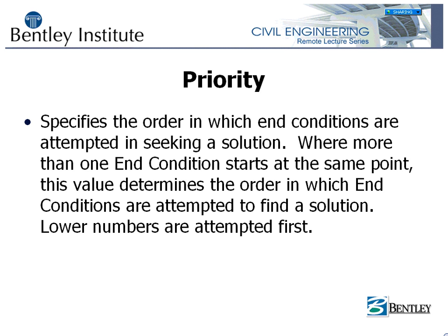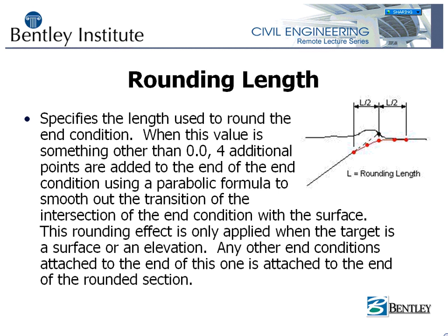And my final definition for this morning is a rounding length. We have the ability to do slope rounding now, which is just kind of neat to do because it happens on a daily occurrence, and many agencies require that you do slope rounding. And so we can set up a rounding factor, and it'll round our slopes in so we get a true world condition for our design there. And we'll touch on that in just a second.